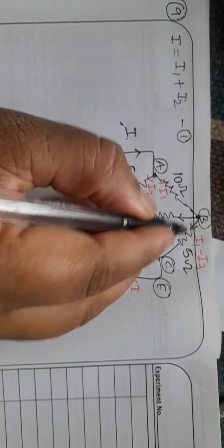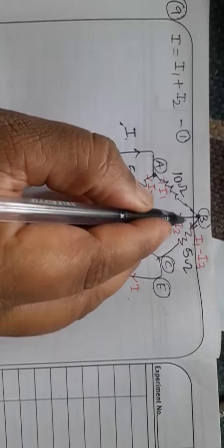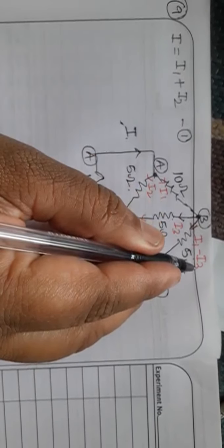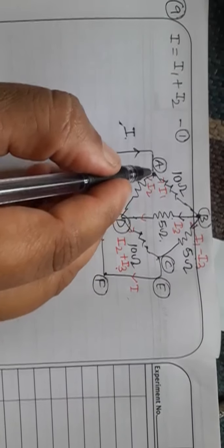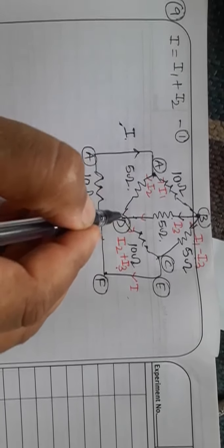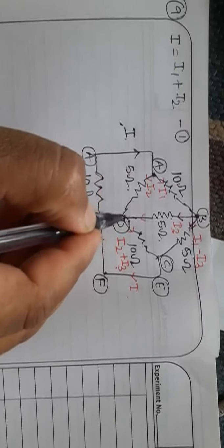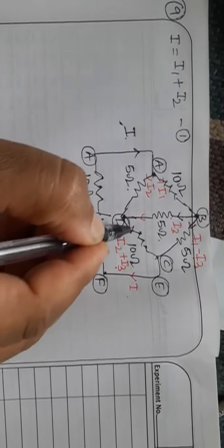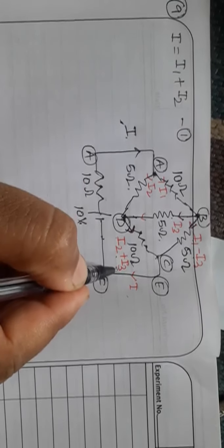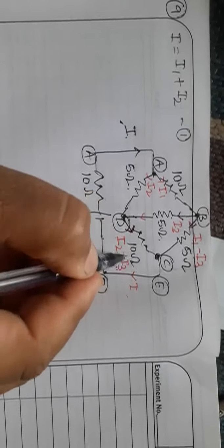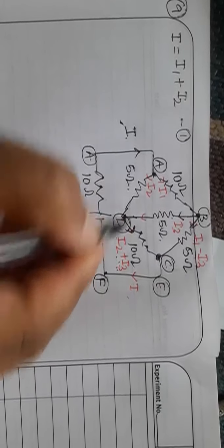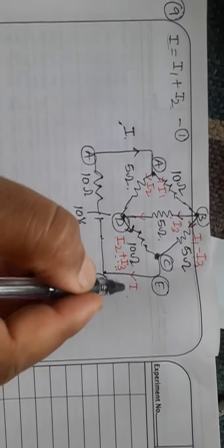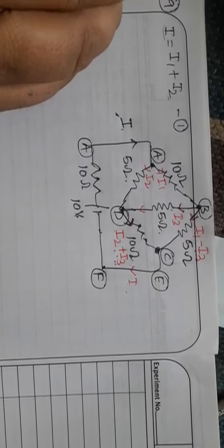The current that moved out of I1, this is I3, so this will be I1 minus I3, because from I1 some of the current moves this side. This side is I2. When this current comes this side, the current from above also comes, so both will be added, as you have studied. The total will be I2 plus I3. Again at this point when these two meet, minus I3 cancels out, so again I1 plus I2, and I1 plus I2 is nothing but equal to I. The same current.